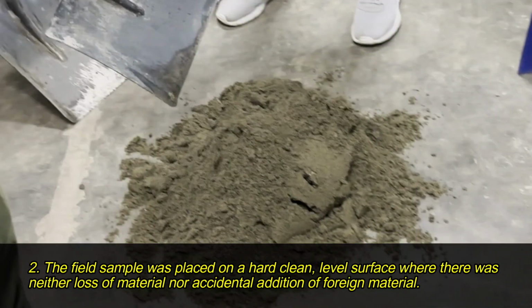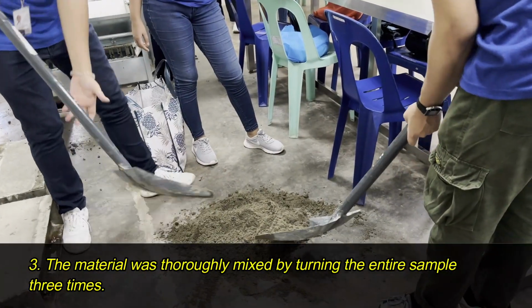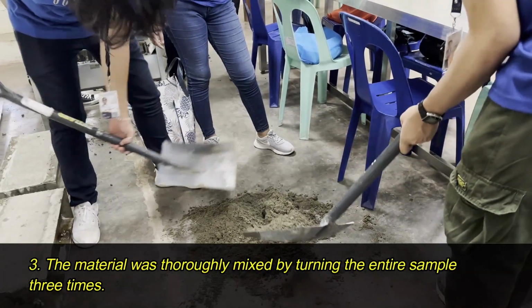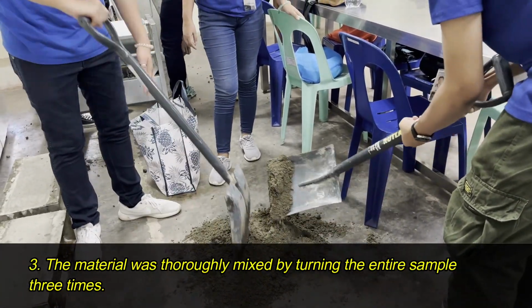Second, the field sample was placed on a hard, clean, level surface where there was neither loss of material nor accidental addition of foreign material. Third, the material was thoroughly mixed by turning the entire sample 3 times.